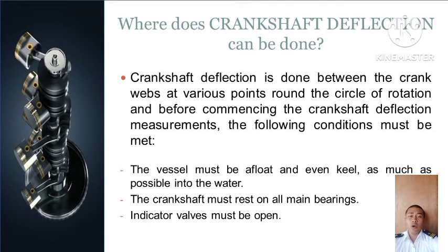So next is where crankshaft deflection can be done, in what situation or in what area. Crankshaft deflection is done between the crank webs at various points around the circular rotation of the crankshaft. And before commencing the crankshaft deflection measurements, I will mention the following conditions that must be met.